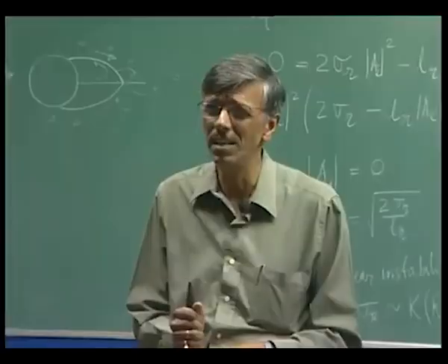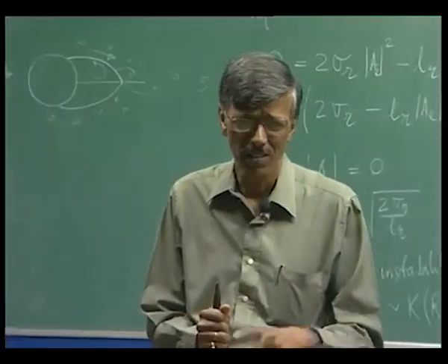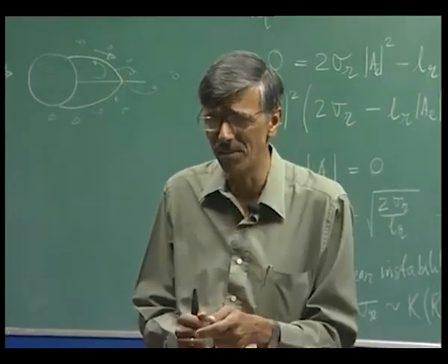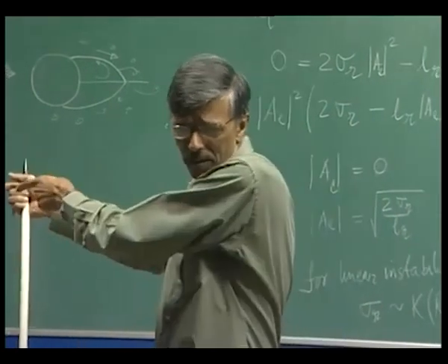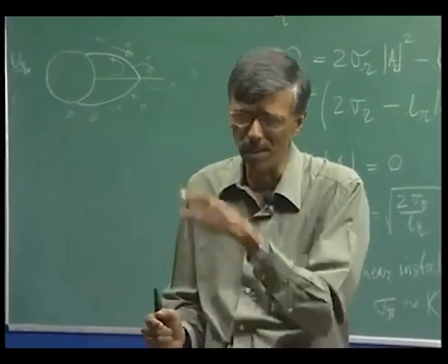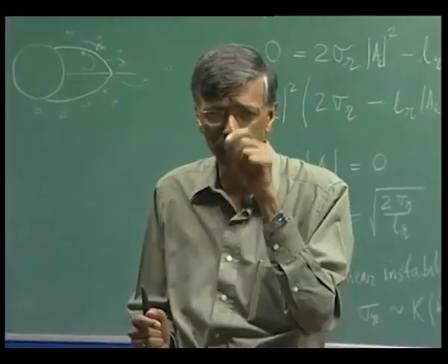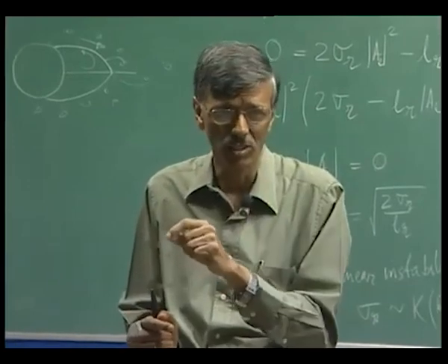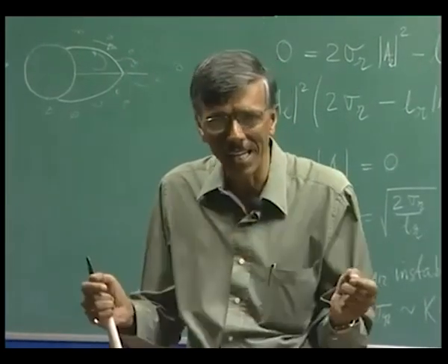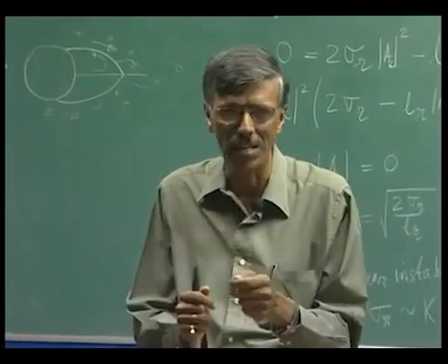So, basically to understand this nonlinear action by putting in a probe and measuring is rather difficult, but if I put it far downstream, because Strykowski and Sreenivasan mapped the region where you have to put this control cylinder, so if I put it beyond that region, then I can study the wake.